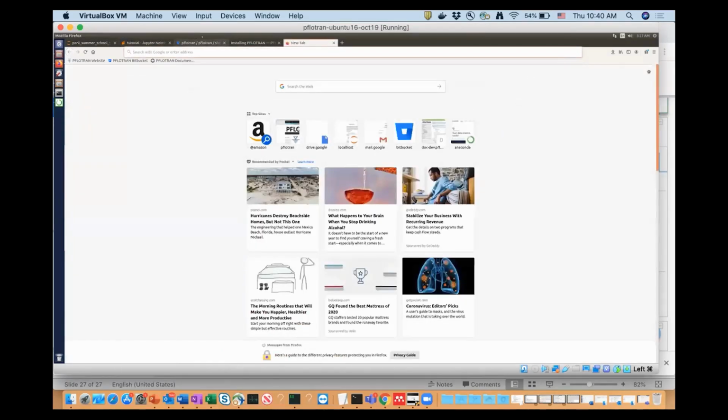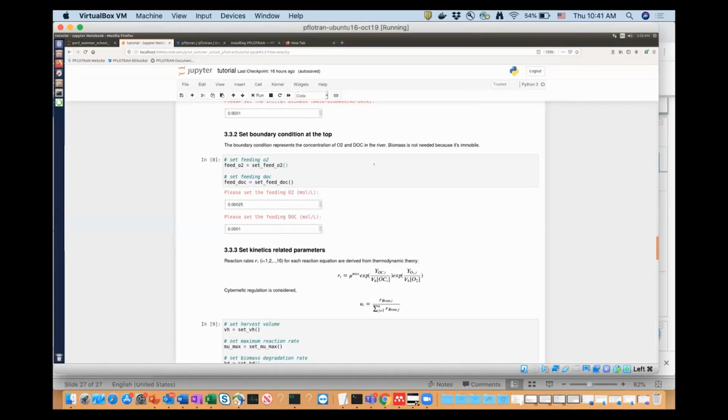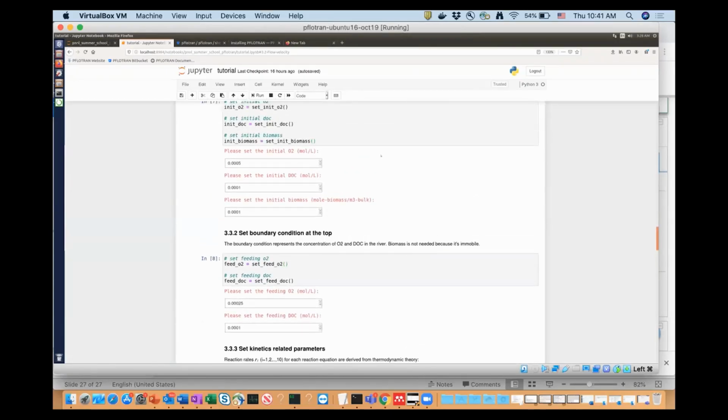Yeah, there were quite a few questions about the grids and how you choose the grid resolution, whether you can do variable spaced grids, and what kind of grid it is. I believe PFLOTRAN is finite volume, if I'm correct. For the grid dimension, our problem is a small 1D problem, so we can choose a very small grid dimension. Here I chose 1 centimeter.